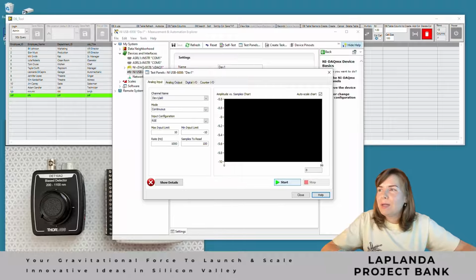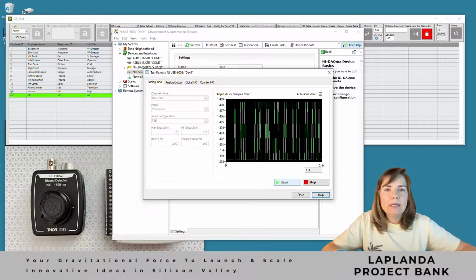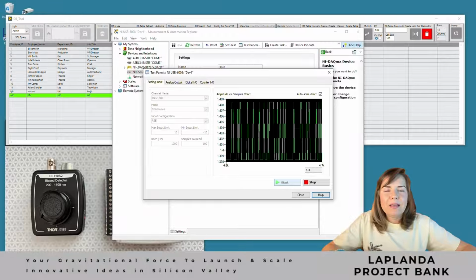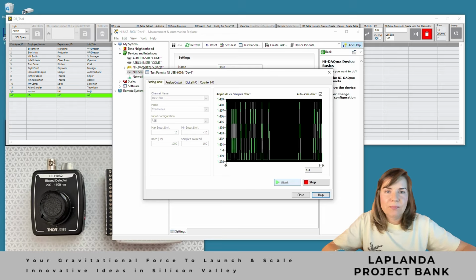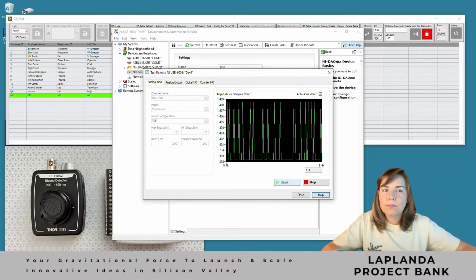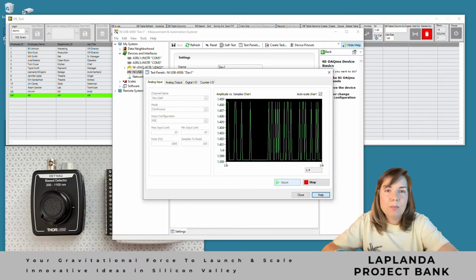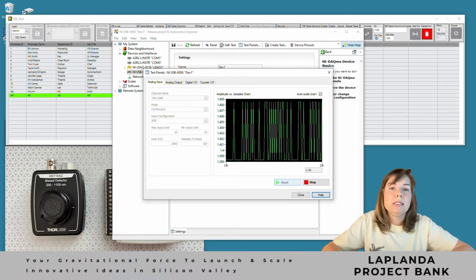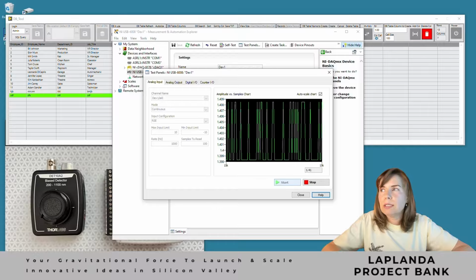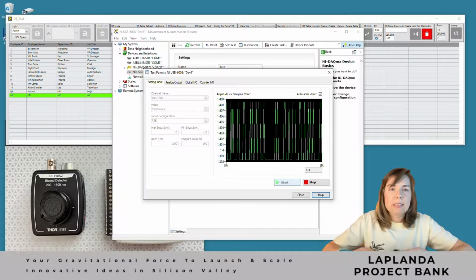I run the program. On the left side of our graph, you can see the voltage values from our photosensor. And right now, these fluctuations are between 1.3 and 1.4 volts. Let's call this white noise, something you cannot completely eliminate, something that is always present in our system as an imperfection. So fluctuations of about 0.1 volts. Let's remember that this is our white noise.